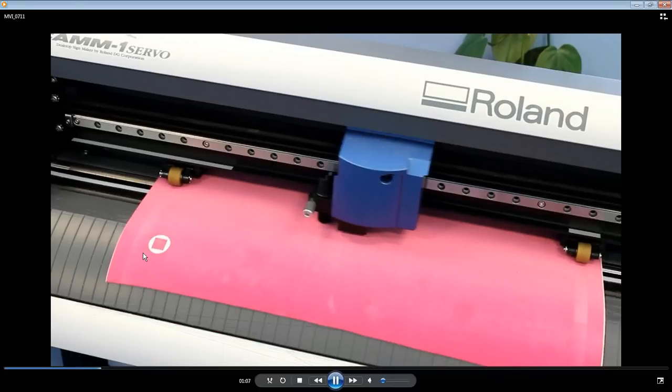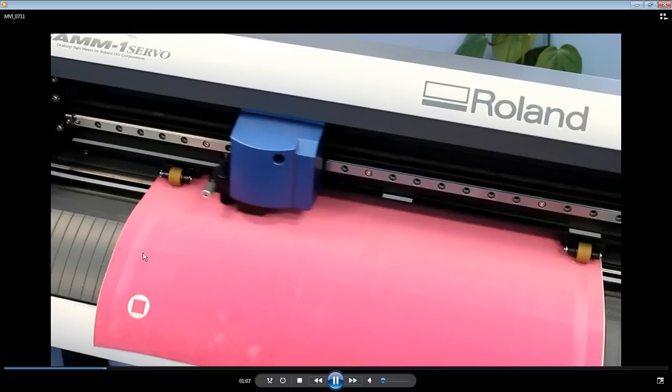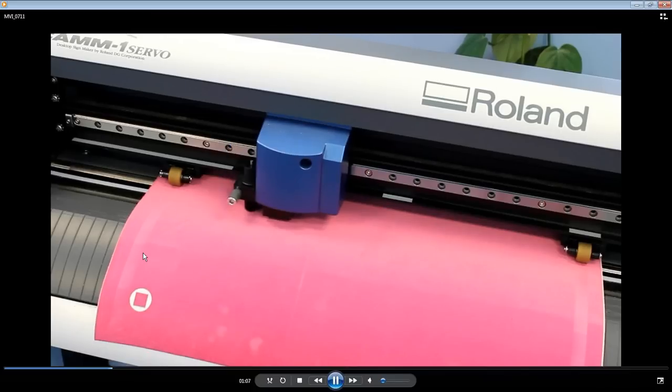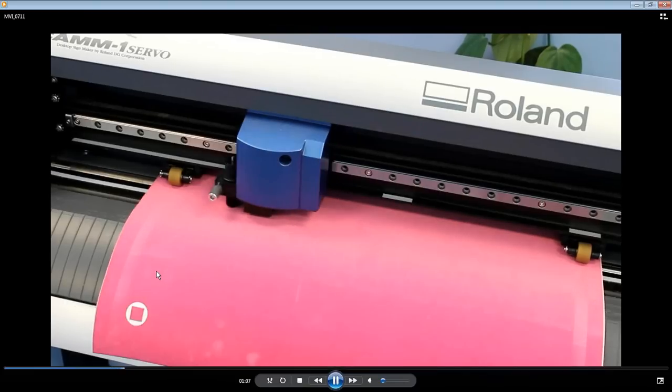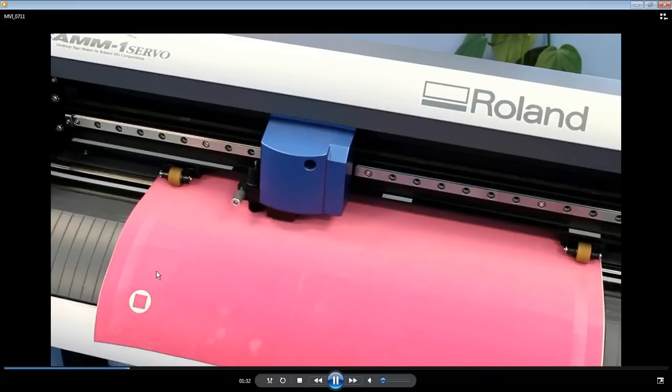And there are several tests that you can run with the cutter itself. You see down here in the corner the little test cut that I did before I ran all this. There's several ways to adjust that offset and test to make sure your cuts are complete, and look at the corners of that circle and square design it does to make sure that you've got a good, accurate offset and then your cuts are completing. So very important to do that.